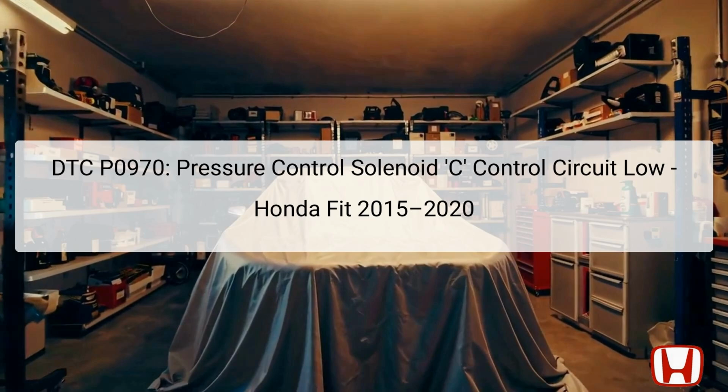The DTC P0970 indicates a problem with the pressure control solenoid C control circuit in a 2015 to 2020 Honda Fit. This code suggests a low voltage issue originating in the electrical circuit connected to the solenoid.